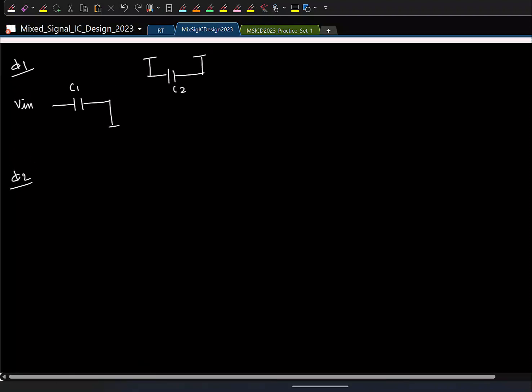And for that, I'll take a switch capacitor amplifier as an example. I'll not draw the complete circuit, I'll draw it in the two phases. In the phase phi1, I know that I am sampling the input onto the capacitor C1. What do we do for this capacitor C2 in the amplifier? We reset it, we want to clear its memory completely. In phase phi2, what do we do? Connect C1 to C2. We basically transfer the charges in C1 to C2, and for that we take help of the op amp.